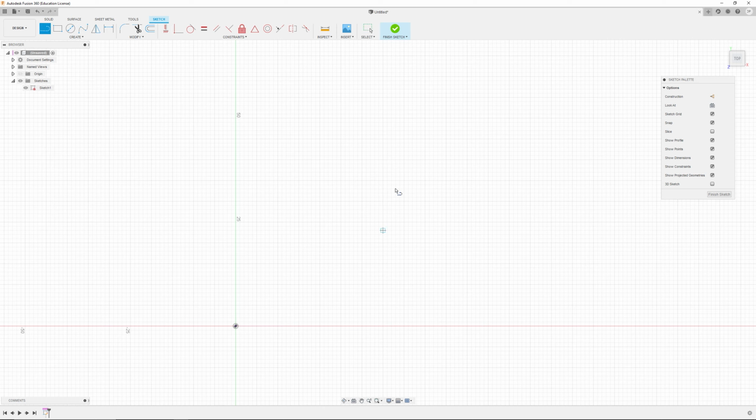Your placement of your sketches is very critical. It always needs to have some sort of relation to where the origin is. If you do not, so for example, if I do something like this, and again, I'm doing an example instead of doing what I said I was going to do, but regardless, it's all in the name of science. If I define this, it still shows blue.